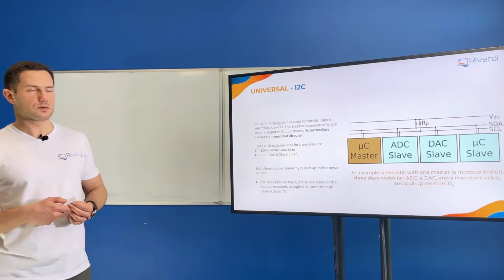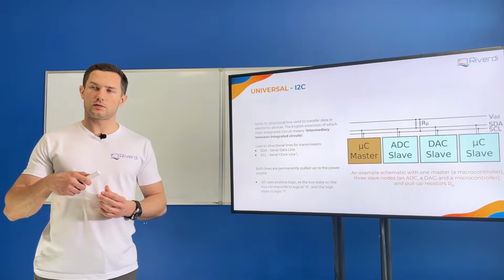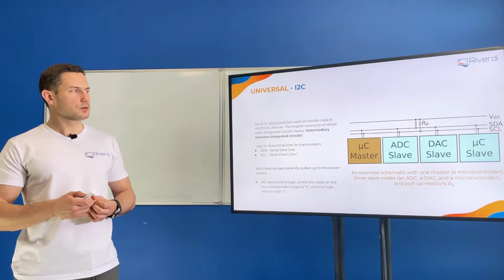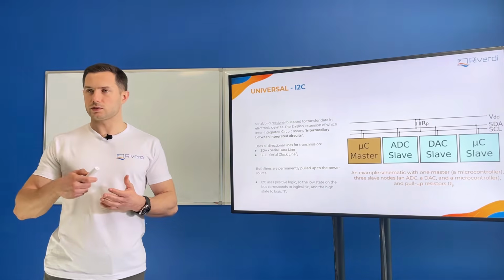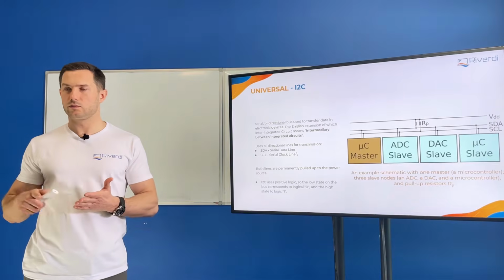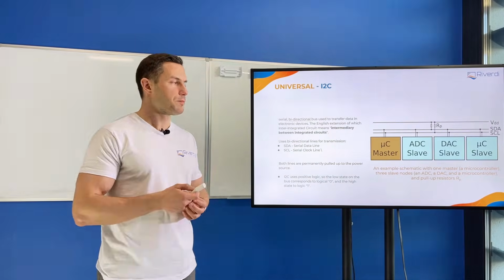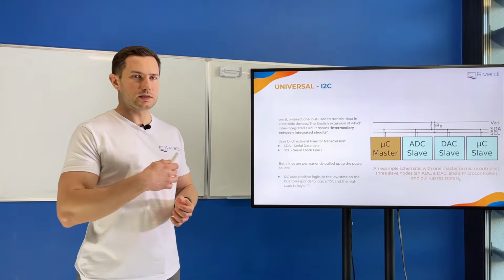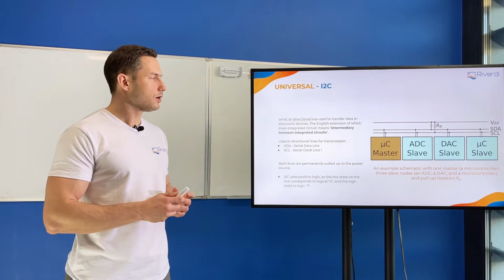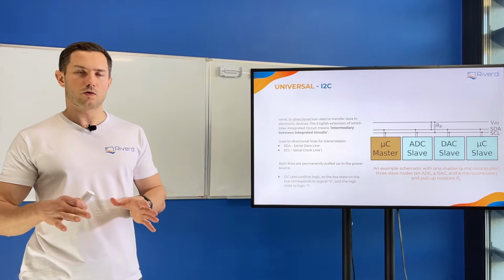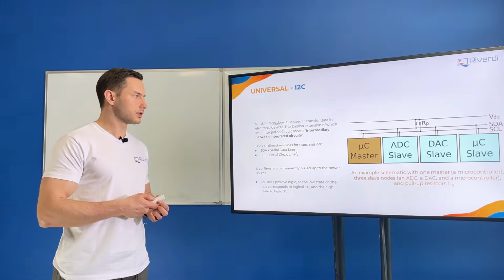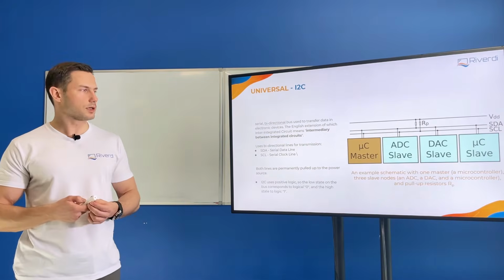This interface is very popular in a display world for the touch screens. Yes, so most of the embedded touch screens that we use, they have I2C interface, because the touch screen does not generate many data. We have only coordinates of the finger or few fingers at most that need to be sent back to the microcontroller, to the processor of the device. So the slow baud rate is well enough for the touch screen, but not enough for the image.